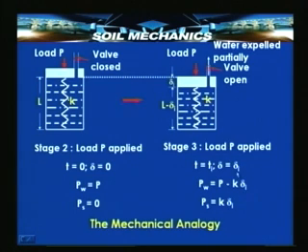So, corresponding to the compression delta equal to delta_i, some intermediate level of compression, the load carried by the spring would be K into delta_i, where K is its stiffness. So, the load carried by water is total load minus K delta_i. This is an intermediate stage, and there will be several such intermediate stages corresponding to several levels of delta_i, and it is this delta_i which we want to compute corresponding to any time t_i, and that is where the mathematical formulation of one dimensional consolidation helps.